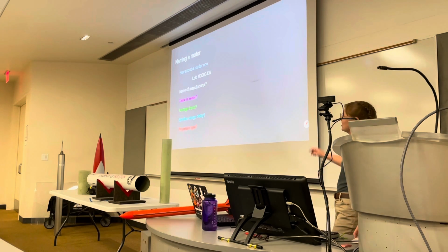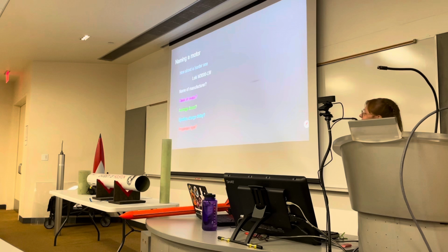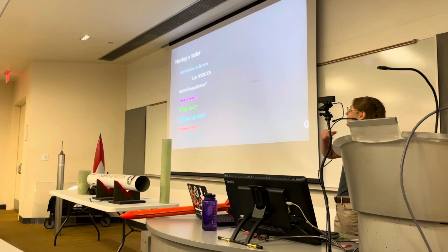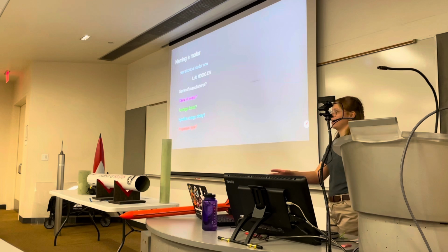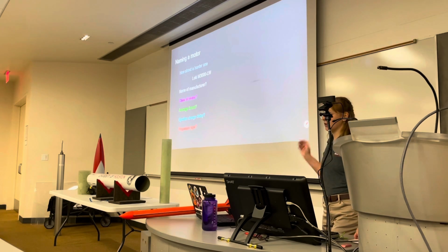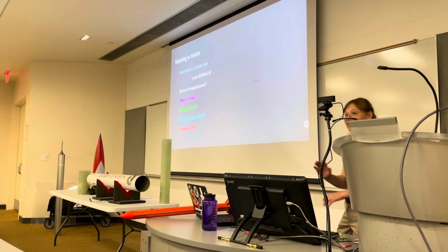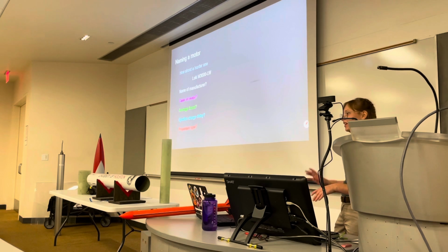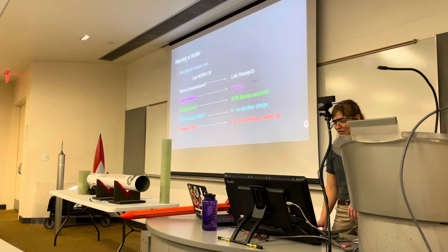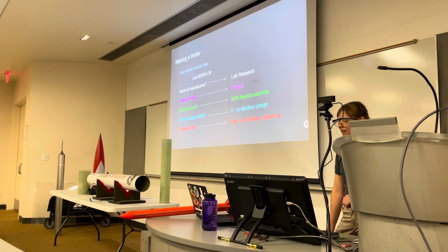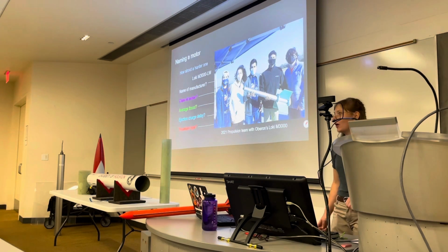All right, what's the ejection charge delay on this? There is not one. Good. So it's not L. Good guess though. It's an M-class motor. It doesn't have an ejection charge. There's no number. 0. And what is the propellant type then? LW. All right. So looking that up, LW is Loki White. We got everything correct there. Oh, and guess what? That's the motor we use on Oberon.